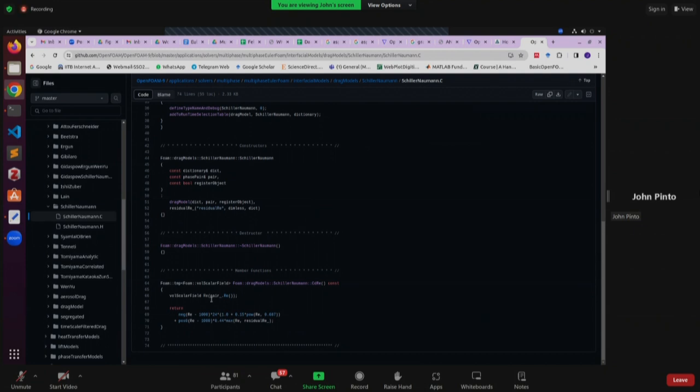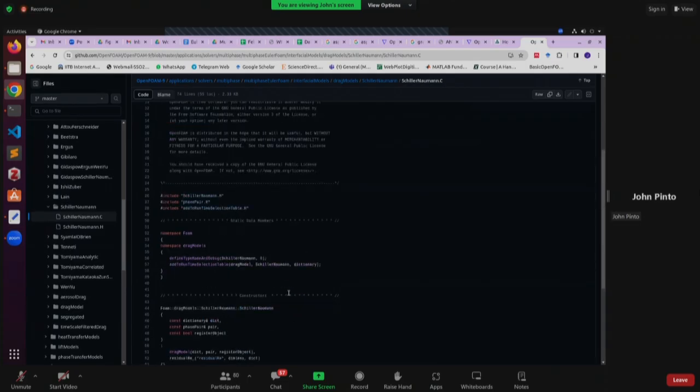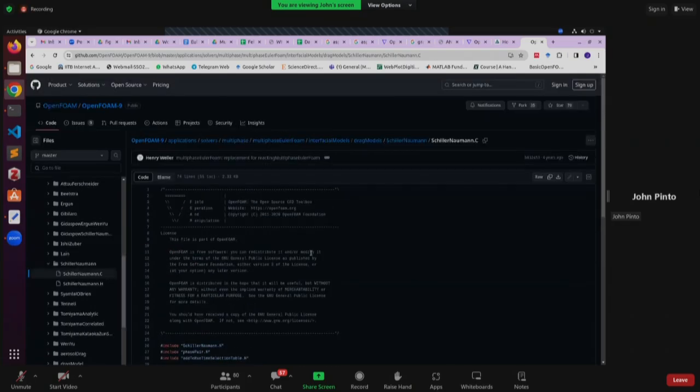So you can look this up. In some cases, they would also have specified the reference for this. So you can read up more on what that drag coefficient is and how it computes drag. And as Sir has already mentioned, the Re is based on the diameter of the dispersed phase. In this case, the air.